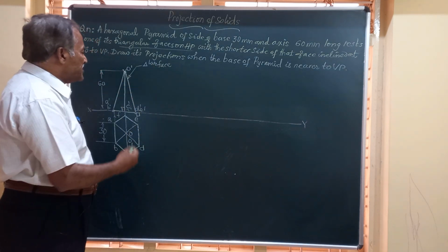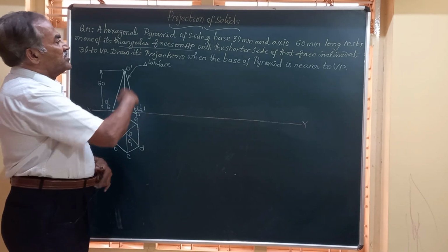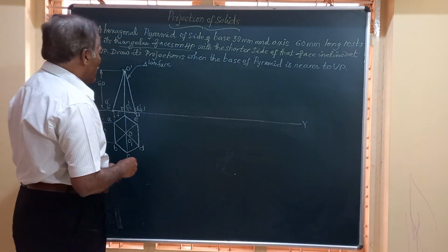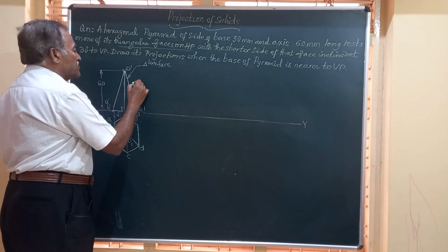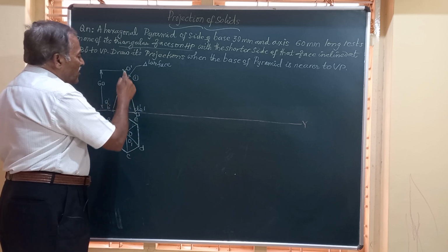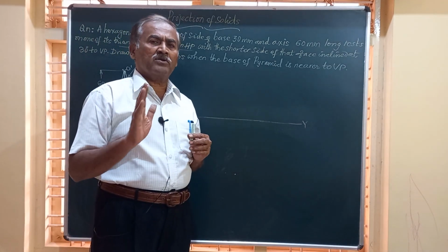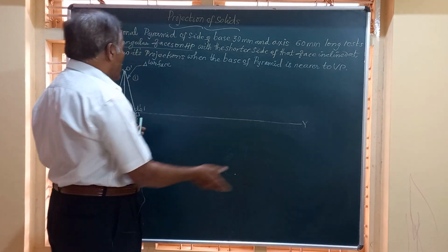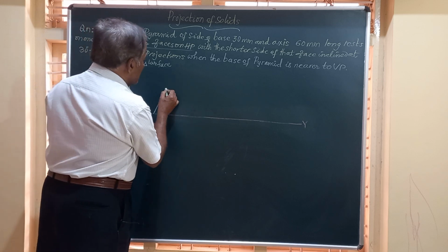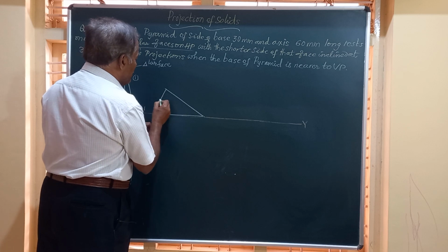So what is the position? It's at an angle to the horizontal plane, but it should lie on one of the triangular faces. So friends, if I call this figure 1, I am going to redraw this figure such that the last line O dash, D dash, E dash, representing one of the triangular faces of the solid, is on HP or on XY. Friends, I am going to complete this figure like this. I'll also tell you how to complete that.